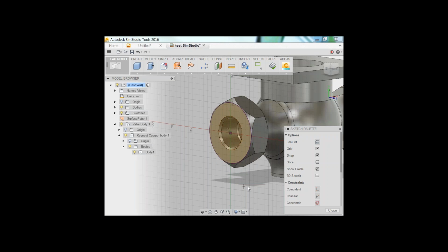I'm going to throw up a quick warning in here, just because this works in SimStudio tools, but for some geometry, like if you're working in Pro E, I know that sometimes the tolerances will be off, and then you might not get the void fill. So that one always scares me. But go on, James. Good idea. No, definitely, and I agree. Sketching on surfaces, now this is a completely flat surface where you can kind of guess where the geometry is going to be. So this is a good example of one where sketching would be easy.